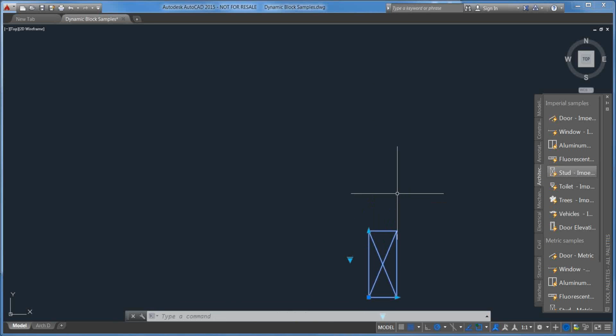So the block and the line work itself is whatever you want it to be. Literally whatever you can draw, you can put into the block. And then it's a matter if you're putting increments or whatever, it's using either a predetermined increment or what they call a list. Because 2x's don't go in a set order, they go in half-inch increments and then they drop another quarter off of that, they go 3/4 inch increments. So you might need to build a list instead of just a standard increment.